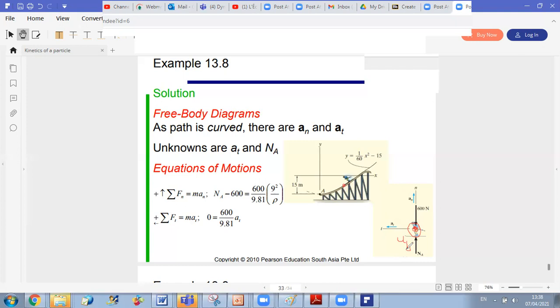Do you have any force along UB here? When UN and UT contain all forces, you will not use the sum of forces along B equal to 0, because all forces are already in the UN-UT plane. So there is no need to project along UB. This is the case here, which was not the case in the Formula 1 example. In the Formula 1 example, the normal has a projection along UB, so you will need the equation along UB.